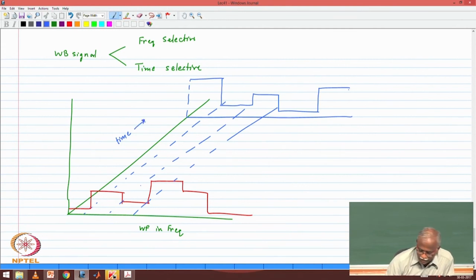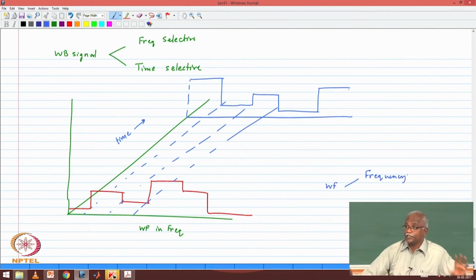so this is water filling over frequency to achieve maximum capacity across the different subbands, and across time, because your frequency response of the channel is changing, and therefore your subband, because subband is what will achieve capacity. So basically multi-carrier techniques, but you keep adjusting the power level as you go.